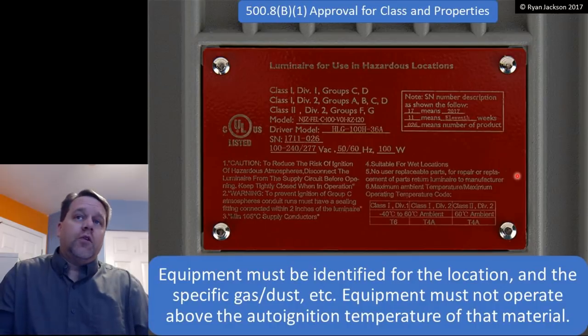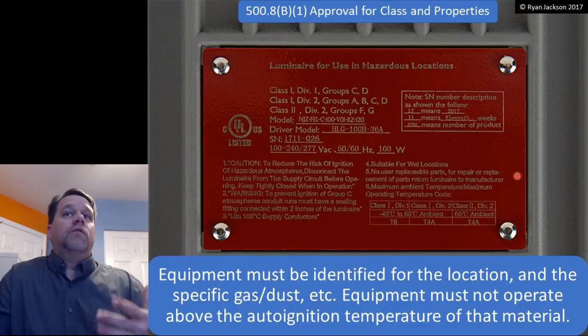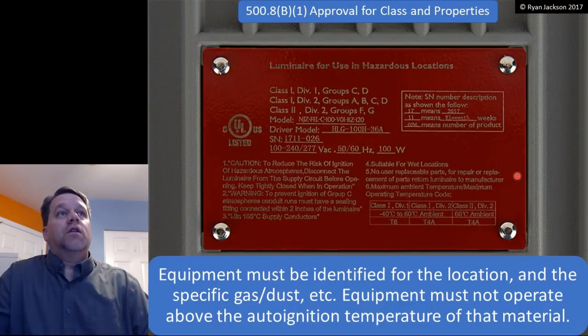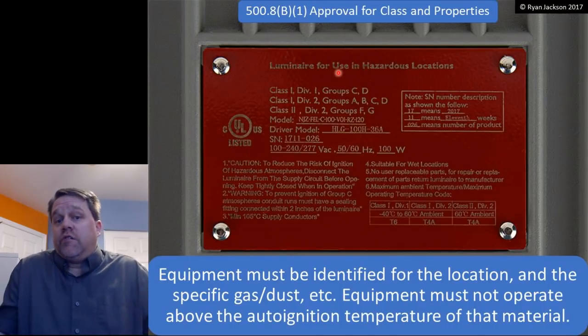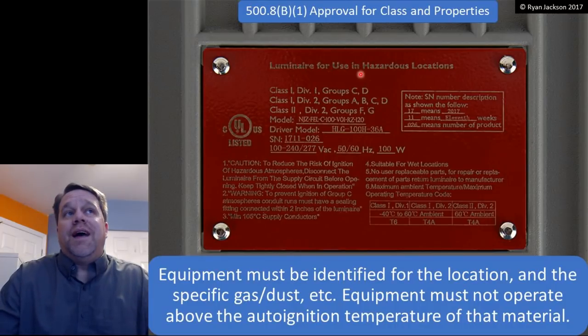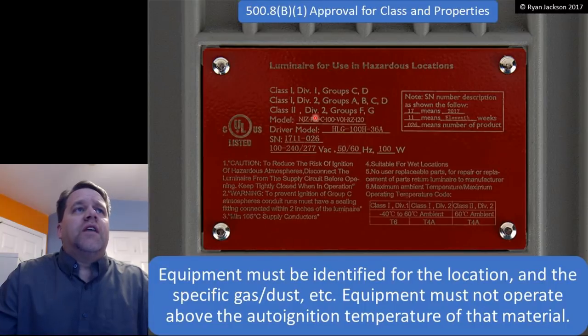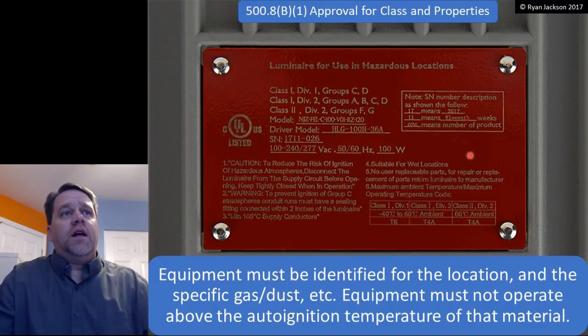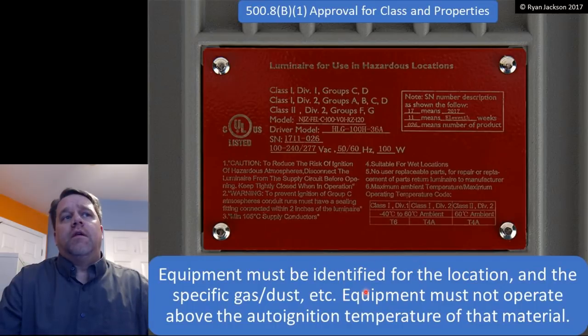And in order to know the group, I need to know the specific chemical compound that drove the hazardous location classification. So, can I use this in an area that's hazardous due to the presence of acetylene? No, because acetylene is group A. So I can't use this in a group A environment. Class 1 Division 2, groups A, B, C, and D. Class 2 Division 2, groups F and G. So there you go. It has to be identified for the specific gas, dust, etc., and it must not operate above the auto-ignition temperature of that material.